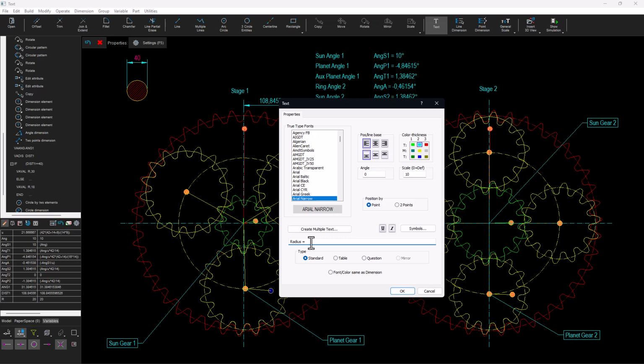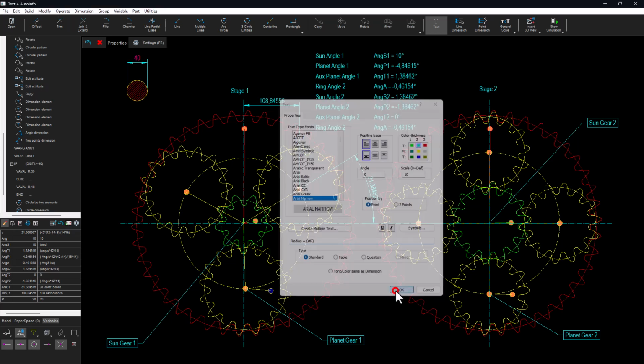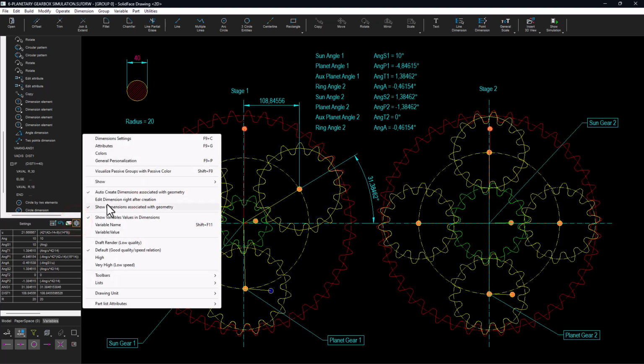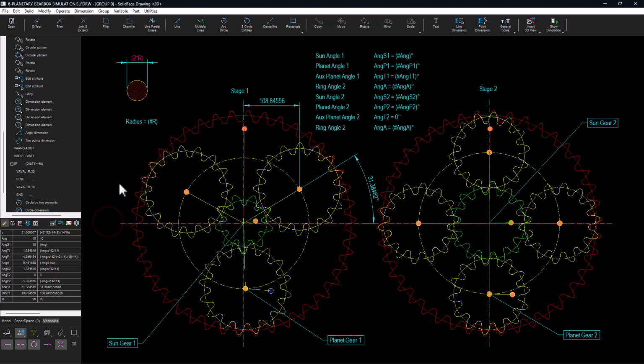Now we are going to display a message every time the variable dist1 is less than 24. Remember, instead of displaying a message, it could be an action to abort the simulation, for instance, indicating that a collision occurred.